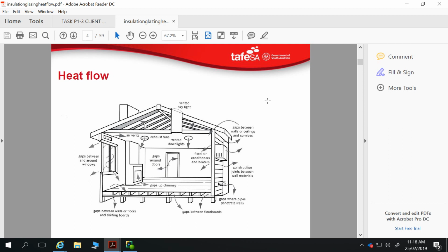That approach to energy efficiency doesn't like air leakage very much, and that is certainly a very important concern if you are going to be air conditioning or heating a space. Also, if you get your orientation really good, then you also want to be minimising your air leakage, because you've got your building performing really well in a passive sense, and you want to contain that.